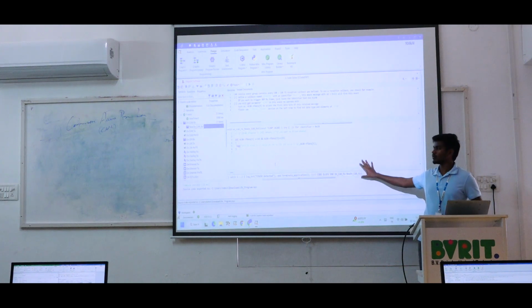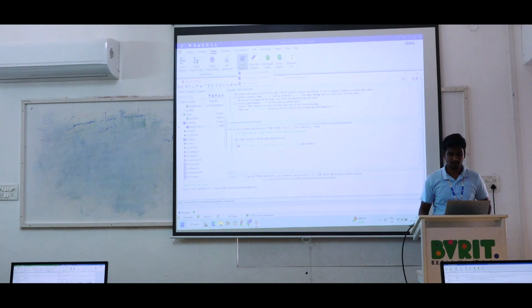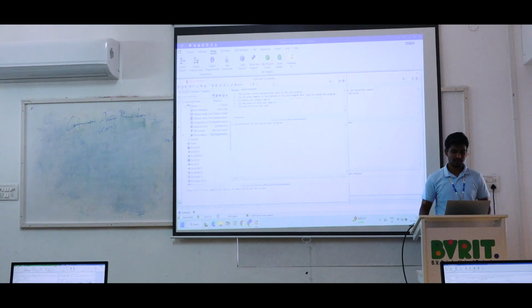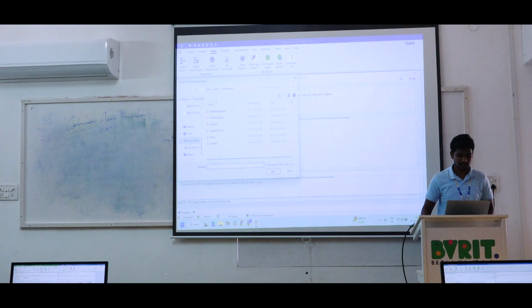Now if you want to import this again, you want to add this, then probably I will open a new code editor, which means you can add a second code. Add C code editor is there now. Just open it, it shows an empty code, in which the onstart will not do anything. On this same side, before save source, you have the import source. Just click it and then import the files you have.